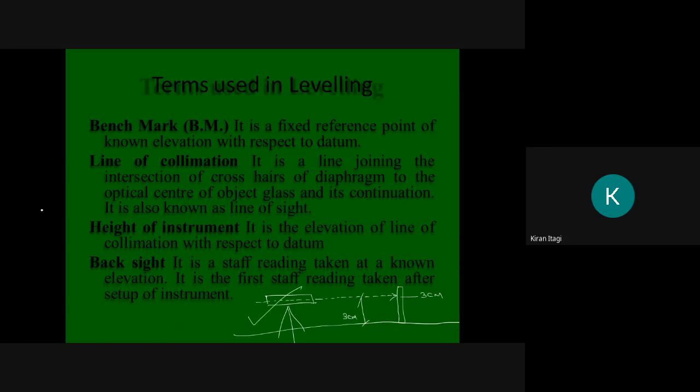Next, backsight. It is a staff reading taken at a known elevation. It is the first staff reading taken after the setup of the instrument.